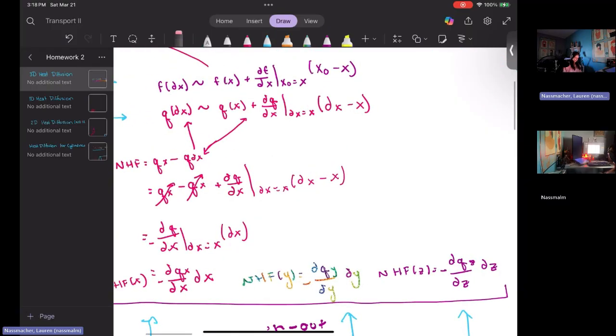So this is the general format of the equation that we want to use, which is that our heat flow at the change in our x direction, or whatever direction you're going, so this could be for the radius, for the theta direction, for the z direction, is relatively equivalent to our heat flow in our original direction x, plus the change in the heat flow over the change in the x direction, where the change in our x direction minus x.